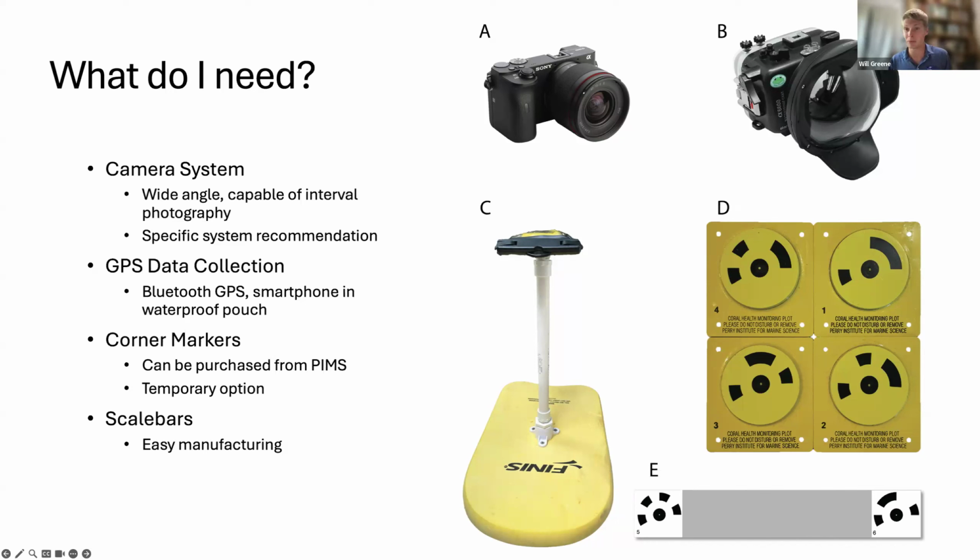And that is something that you will need for any underwater photogrammetry process, not just ReefShape. But what we use is the same type of coded underwater markers that are all unique. Each one has to be a different pattern. And for our scale bars, we just print them on underwater paper and tape them or glue them onto ends of an acrylic scale bar. And then we measure exactly the distance between the 2 center points. Those are really easy to manufacture on your own.